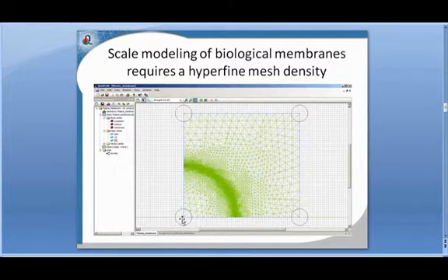So what we're looking at is 1/4 of a cell, and this is modeled in axial symmetry, where the bottom axis here corresponds to the z-axis, and you can think about the cell being rotated about the z-axis that's horizontal, pointing along the bottom of the page with the positive z-axis to the right, and the radial coordinate moving up. In this problem, we have roughly 200,000 nodes. In the regions away from the cell, this is a few hundred nodes, whereas near the cell membrane we have a few 100,000 nodes. So that's roughly 3 orders of magnitude difference in the size of each individual finite element here.